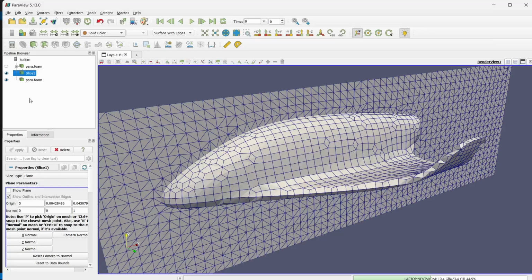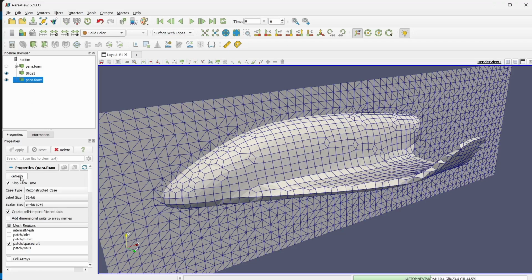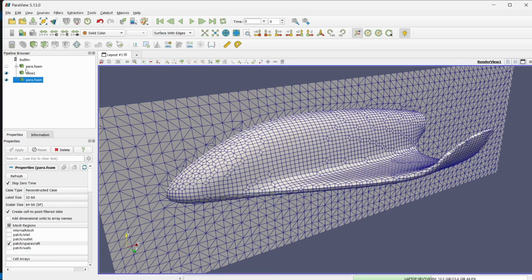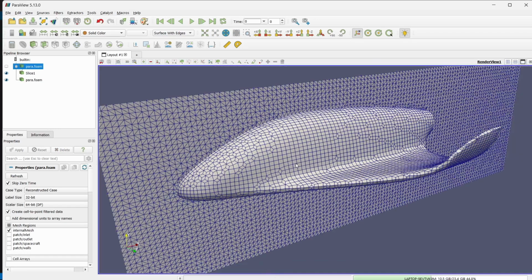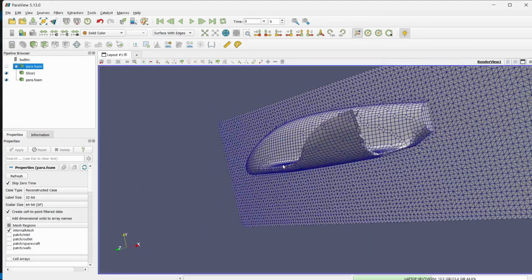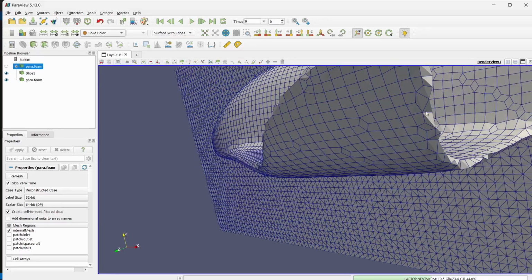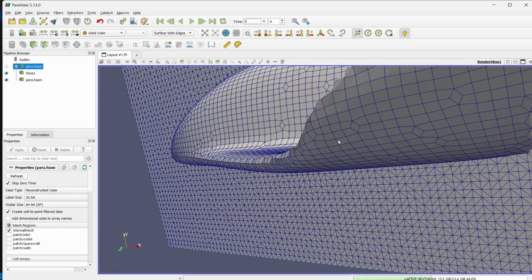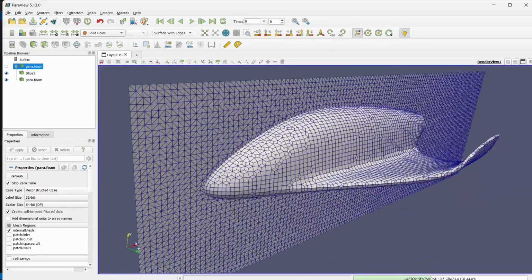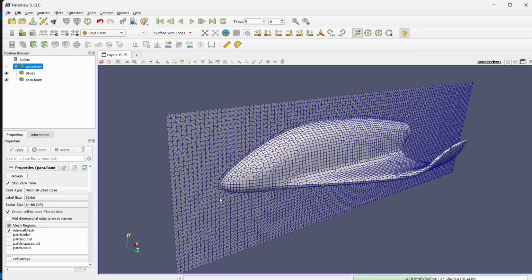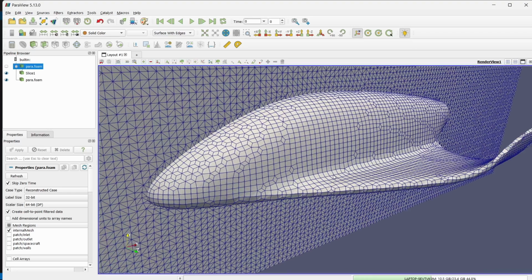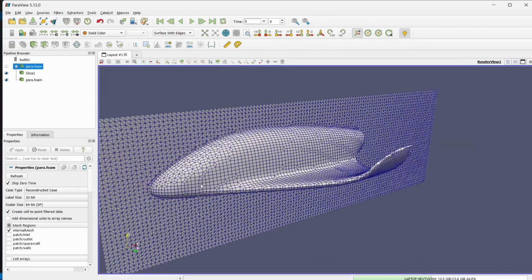You can go here, refresh it. Yes, it's better. Refresh this. Yes, it's better. So this geometry looks much better, even though we have faulty edges at the end. But we will add local refinement to this zone, because if we start refining everything, then it will become computationally very expensive. So we'll just add local refinement.